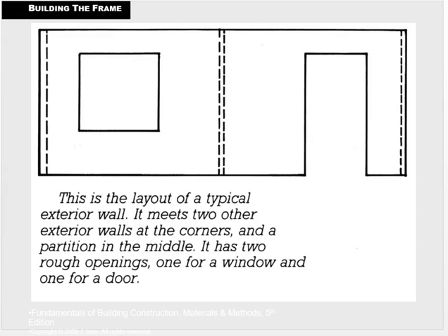So how a typical wall layout would look. So here we just see a schematic of a very basic wall, and these dashed lines are indicating where walls are adjoining this one perpendicular to it. So on the outside wall here perpendicular, there's another wall obviously, and on the outside there's another wall here, and then we have an interior partition that's meeting the wall at this location. Pretend we're looking at the front of a house. This is the right yard wall, this is the left yard wall, and then this is the wall that separates, whatever, the foyer from the dining room. So the walls meeting the exterior wall.